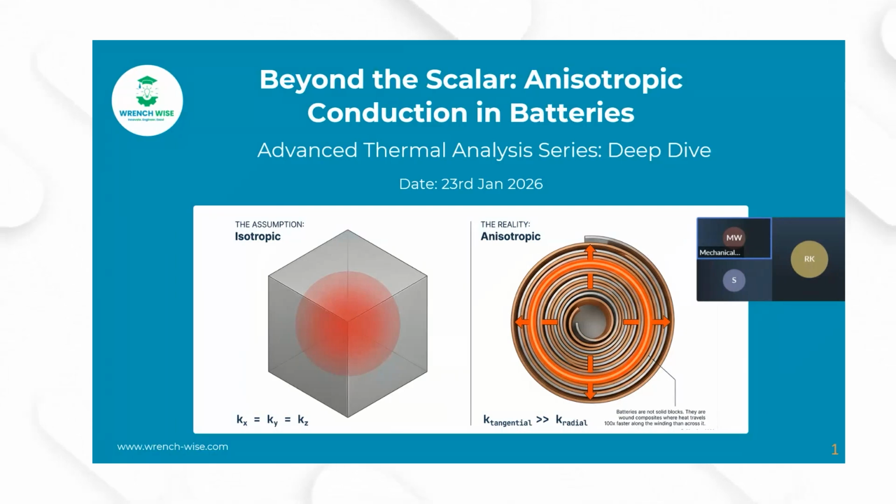In many basic simulations, we treat the battery as a solid uniform block where thermal conductivity is almost the same in every direction. So thermal conductivity in X, Y, and Z will all be equal. This is an isotropic assumption essentially. This simplifies the mathematics to a large extent, but many times in very specific cases in batteries, it doesn't really reflect the physical world.